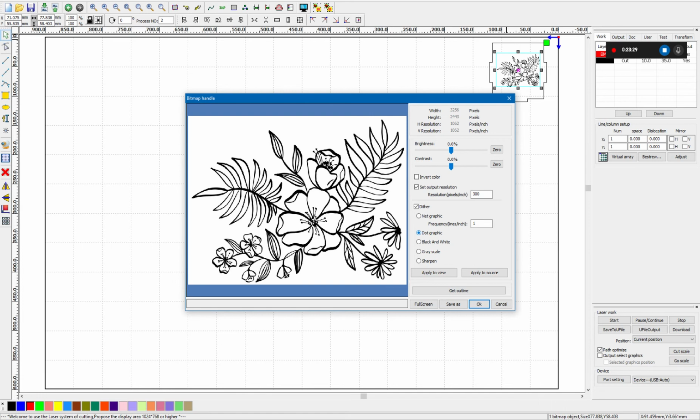The laser can only produce about 150 at any rate. Higher settings simply result in overly large files that can take a long time to transfer and may even exceed the 1 MB size of the memory of the computer in the laser cutter. The bottom right section is the dither controls.